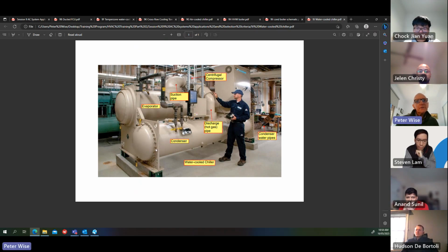And looking at this chiller, this is the condenser. You need access to the condenser for cleaning out the tubes, which should be done every 12 months. So there are all these nuts and bolts on the end here. But undo all that and take the end off so you can get access to the tubes. These end plates, because if you've got cooling towers in the system, it's an open system, these end plates are often made of steel, so they're subject to corrosion. So they want to check those every 12 months as well and see how they're going.